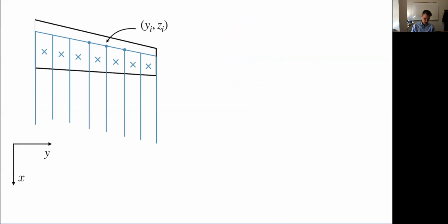X direction, as we've noted, is downstream. This is a standard aerodynamic coordinate system. X downstream, Y is out the right wing, and that gives, by the right-hand rule, Z positive up. That's fairly standard for aerodynamic systems. For dynamics, if you were doing a GNC class, it would be kind of the opposite. They typically do X as positive out the nose of the airplane, Y out the right wing, and so then Z by the right-hand rule will be down.